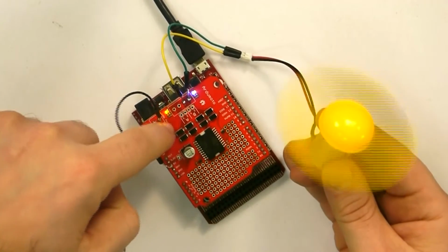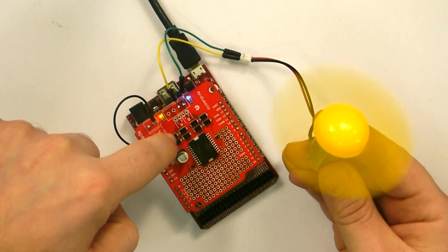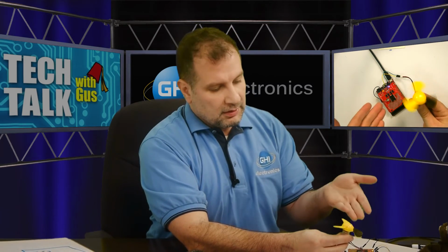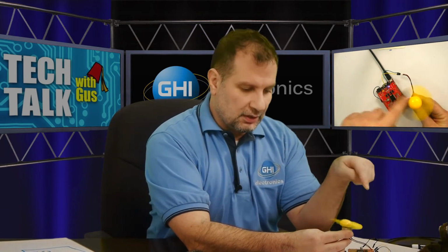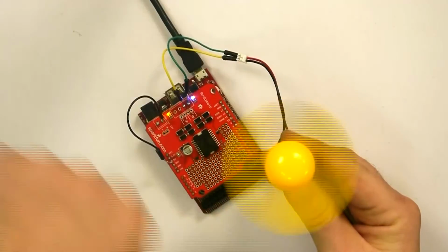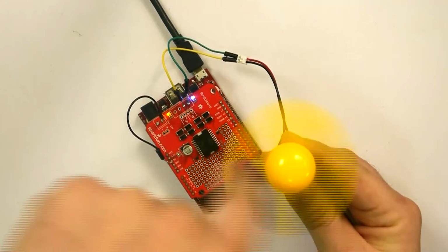These are the diodes we talked about earlier, the protection diodes. You see them down here keeping the circuit safe from the voltage spikes that will be generated by the motor. So in this example, I'm controlling the direction of the motor every 3 seconds, and the speed. So it's spinning this way slowly, but then it's spinning the other way around fast.